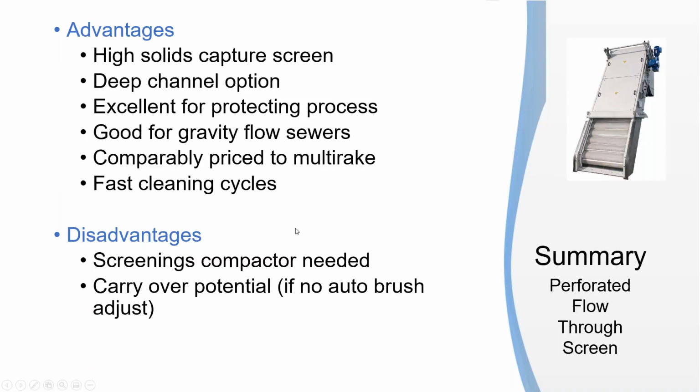Now the disadvantages, it does require a screenings compactor because you're pulling out so much in the way of screenings. A lot of debris will land on the outside of it. It needs to be washed and dewatered because you get a lot of water pulling out. At minimum, a conveyor compactor would be recommended, if not a full-on wash unit.